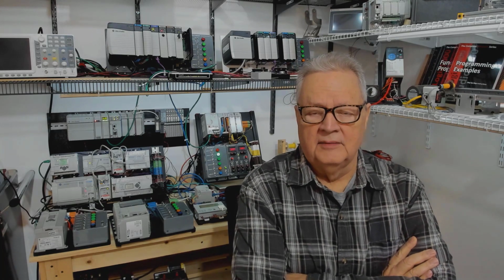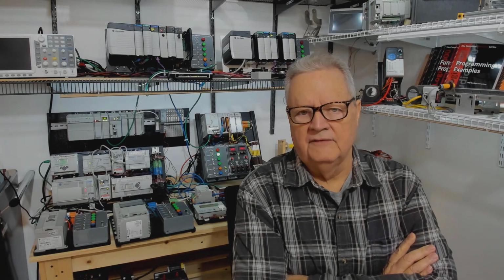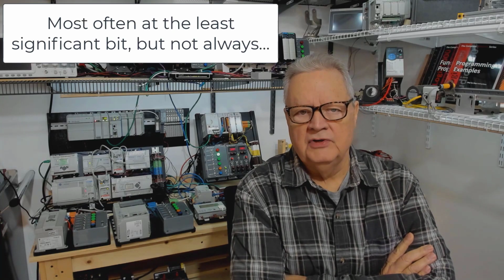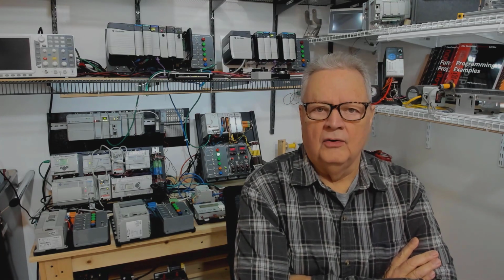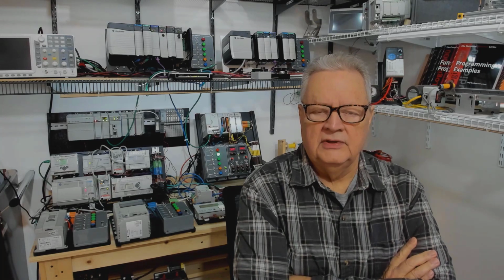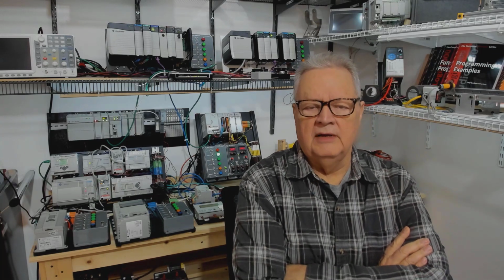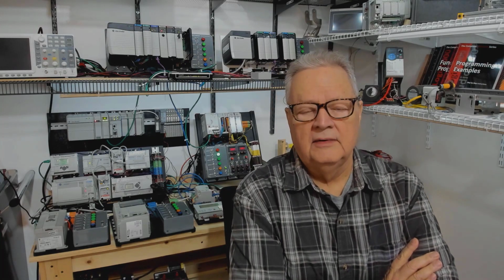didn't even get started with bit shift right, which is actually a little bit more complex. With bit shift left, you're always pushing the bit address value into bit 0, the least significant bit, and then you're shifting a length of bits to the left. They unload when they leave the last position into the unload variable, whatever you named it. In our case, we named it output 0 so we could see a light come on when it unloaded a 1. Keep in mind, if it unloads a 0, it turns the light off.